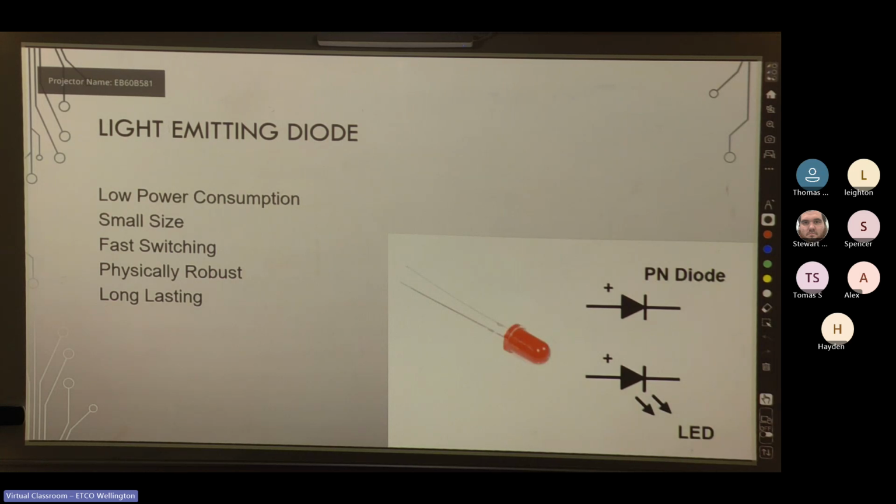So there's a potential for the danger of the spinning machine, accidentally sticking your hand in it, things like that. So it presents a safety issue. The options to fix that are having two fluorescent lights next to the machine, one on red phase, one on blue phase or white phase, so the strobing is at a different rate and it appears that there's more of a constant light. Or we can replace the fluorescent light with an LED, which, because it runs on DC, is a constant light source.